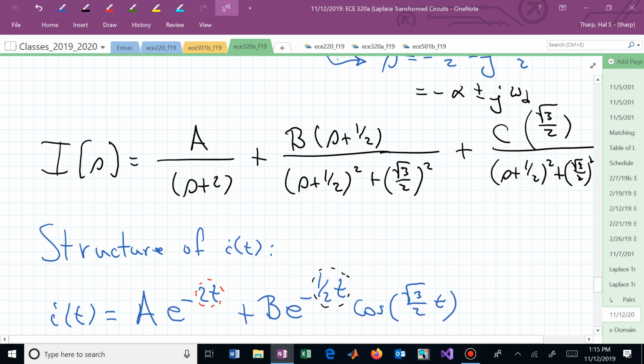Well, let's use the strategy we talked about last time. Let's multiply through by s, all terms, and then let s go to infinity. And here it's actually infinity. It's not 5 tau. We're letting s go to infinity. What happens to the C term? It vanishes. It's C over s, and as s goes to infinity, we don't have C appearing.